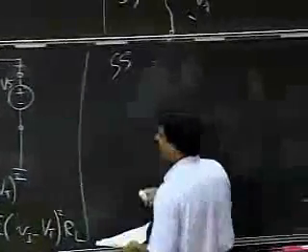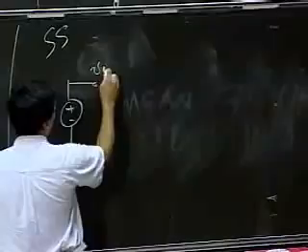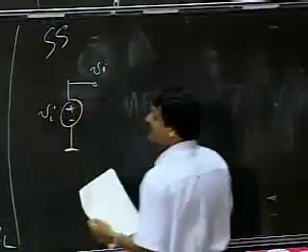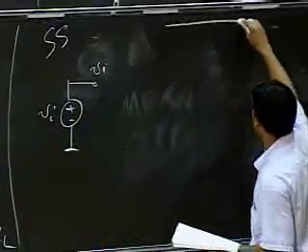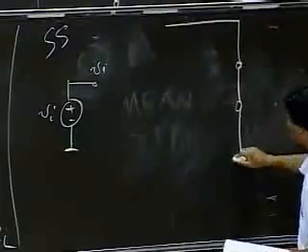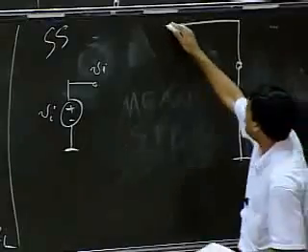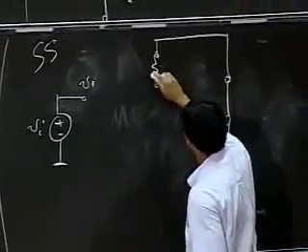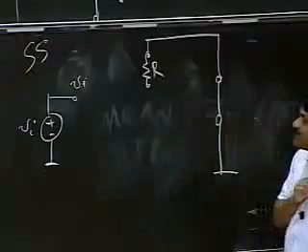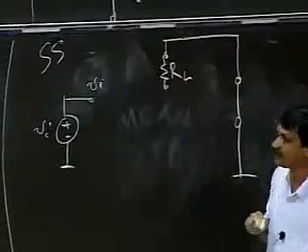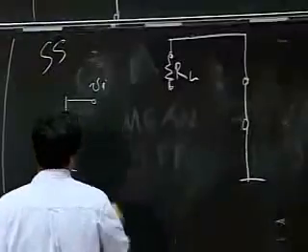So let's do that. For the input, you replace the input with its small signal voltage, because it's sourcing a small change, vi. So that's vi. Then I replace VS with a short. I replace RL with an R, because it's an RL itself for the small signal model.